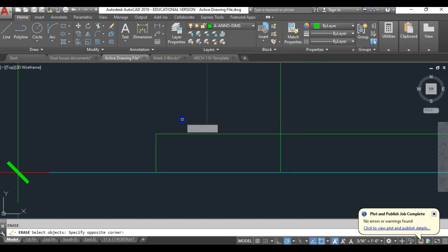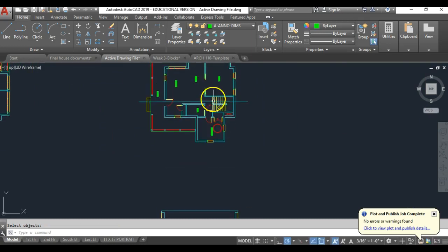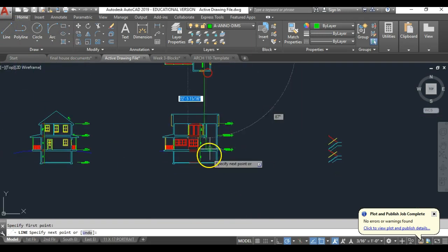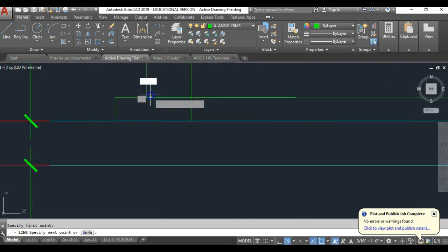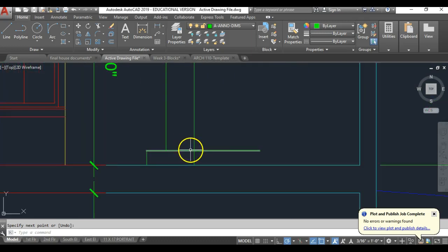Let me erase this just to make sure. I can see because it's going past that line that I didn't hit the snap I thought I hit, which was supposed to be perpendicular. So just in case I misdrew it, it might have been in the right spot, but I'm not 100% certain, so I'm just going to redraw it down. So I make sure I get that perpendicular snap there. There we go. So now I've got a couple extra guidelines I can get rid of.